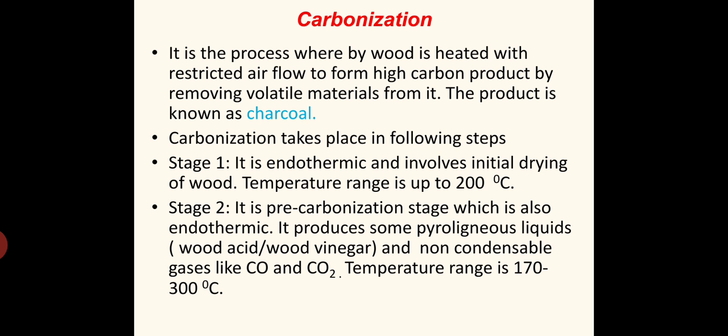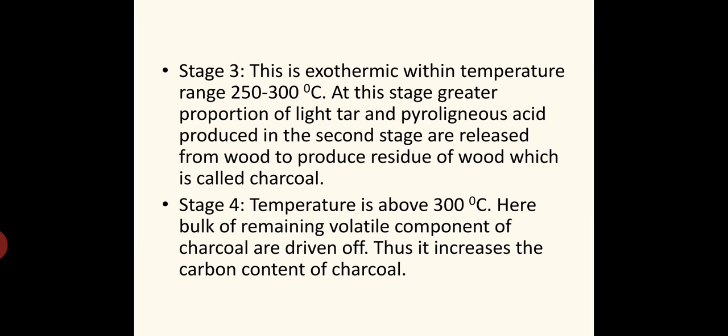See, during the second stage itself, pyroligneous liquids started to separate from the wood, but not in a greater proportion. Along with that pyroligneous liquid, non-condensable CO and CO2 are produced. The pyroligneous liquid produced is lesser in quantity in the second stage, but during the third stage, more pyroligneous acid is produced, so the liquid content is completely removed from the wood. That means the remaining will be pure solid, commonly known as charcoal, in the solid state with high carbon content.